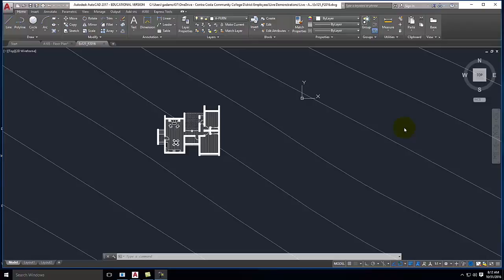But the idea here is that there's always a relationship between the top or the plan view and the side or the elevation view. And if we were traditionally drawing, and we've broken this down a little bit in current technology use, because many times now we just model it in 3D and then we see the elevation as we are modeling. But in the case of the old school way of doing things, if we go way back to when you used to have to draw by hand, this was how you would set up a drawing, or at least your draft version of a drawing. You would draw your floor plan, and then you would pull your elevation from your floor plan. And so I'm going to walk you through how to do that in kind of the old school way.